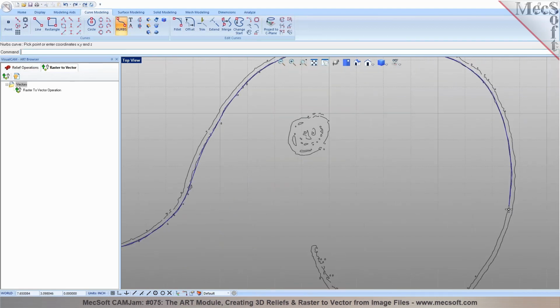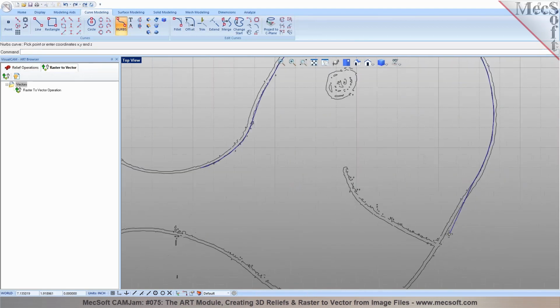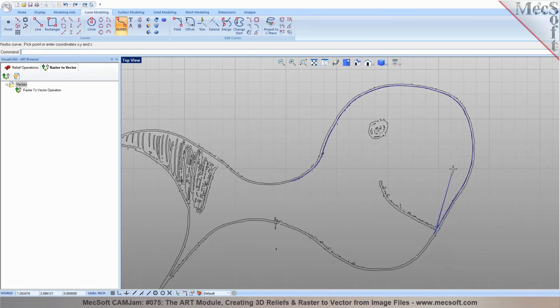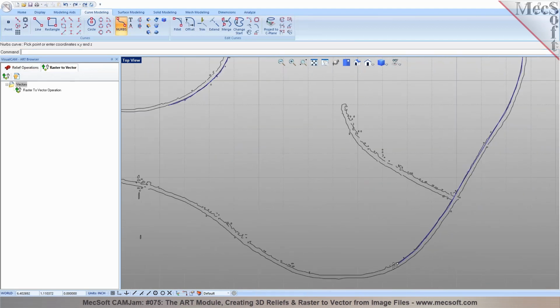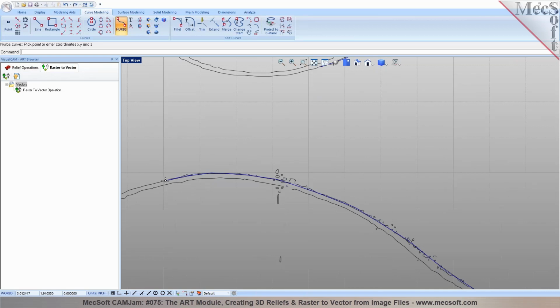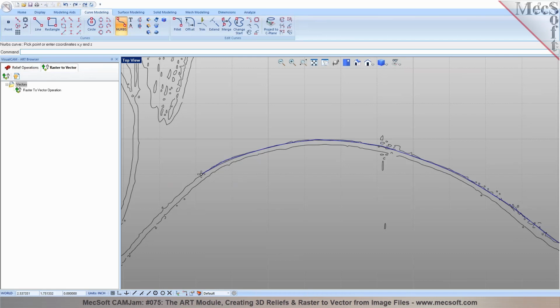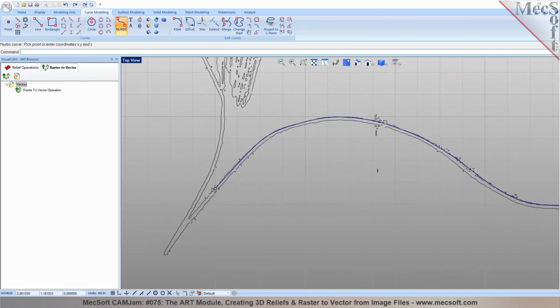So you have a curved outline. I'm going in here and creating this nice little boundary around it to remove a lot of these imperfections. Rather than having to delete, trim, and merge, I could use these tools that are available. NURBS curve is a very nice tool to recreate some of these sections. I could be recreating the entire section because it was drawn by hand, and because of the thickness of the pencil, it's grabbing all of that as a double line, right?